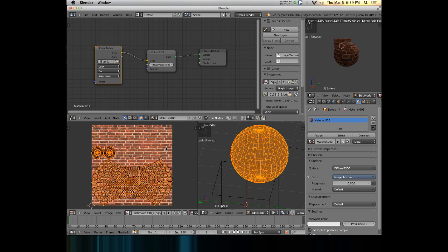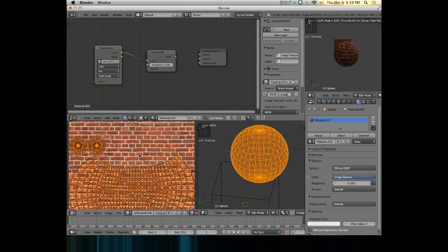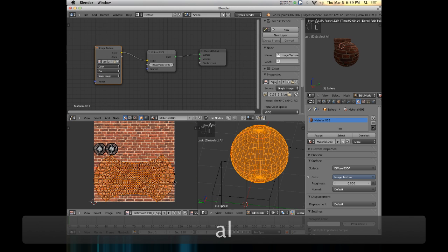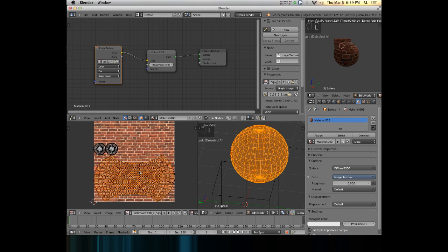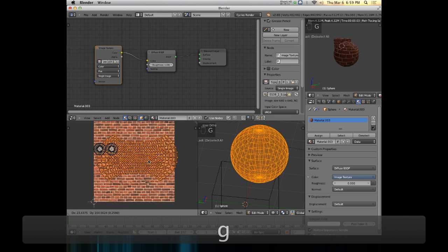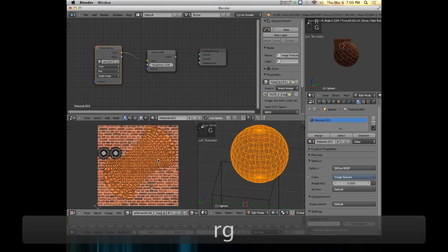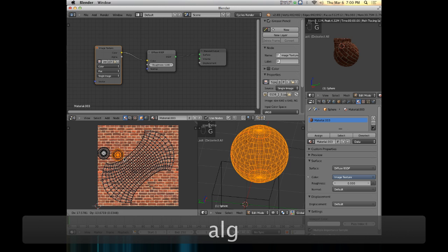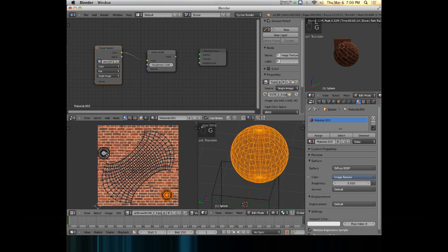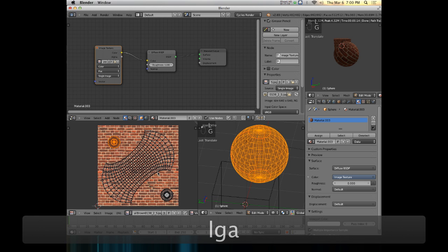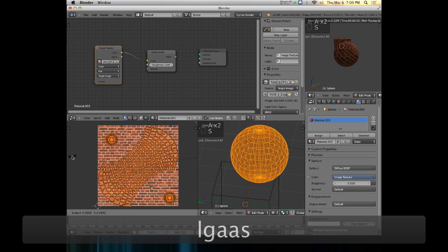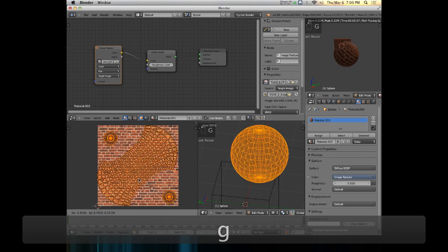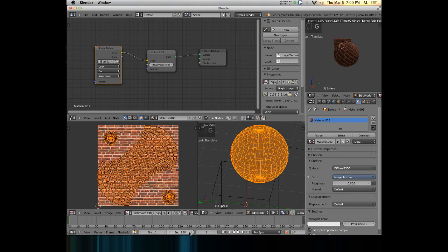More is obviously better, but you want to try to pack as much information into that finite amount of pixels as possible. So one of the things that you'll start doing is taking your UV, what are called islands, or the sections of the UV map, and moving them around and trying to pack them into your texture in a way that allows you to make them as large as possible. So select those, and then I can select everything and scale it up just to give me the most detail that I can get out of this map. Okay.